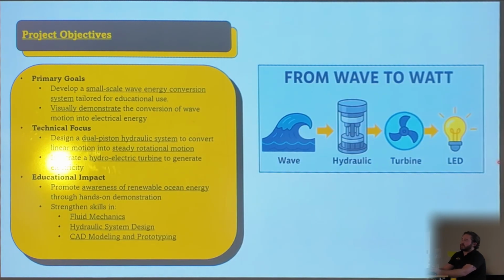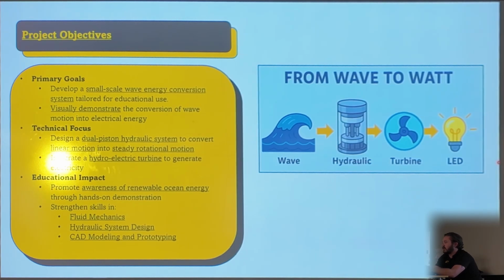So my objectives for this project were to develop a small-scale wave energy conversion system tailored specifically for educational use so that it could visually demonstrate the conversion of wave motion into electrical energy. To do that, I wanted to design a dual-piston hydraulic system to convert the linear motion into steady rotational motion.